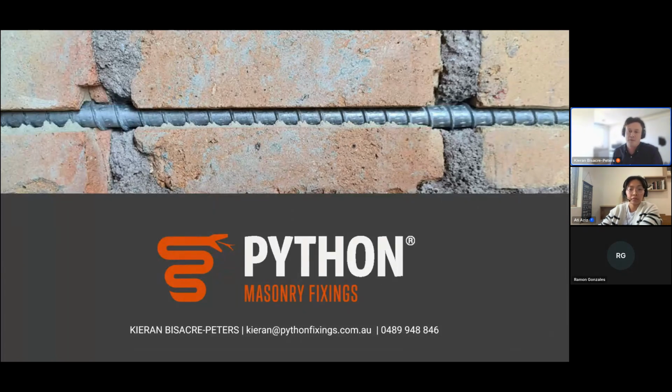Durability wise, they've got the zinc nickel coating system, a galvanic coating system. And we've got extensive durability testing to back that system up. It's a highly durable coating system, about 5 times more durable than galvanization. So yes, they're high strength steel and they've got the zinc nickel coating system on them, but they're not stainless. What was the second question there?